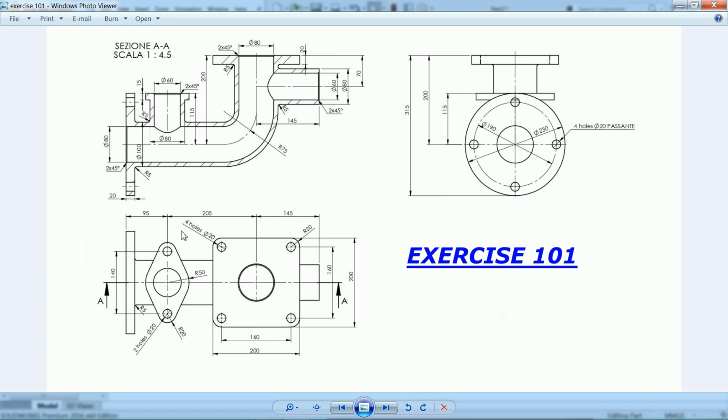Okay, and 95 millimeter from this side. So first we will create a plane, then we will create this pipe 180, then this shape 50 millimeter, this diameter 20, outer radius 20, and pitch 140. Okay, so let's do this.